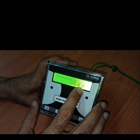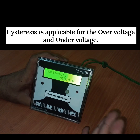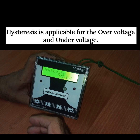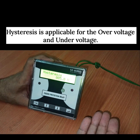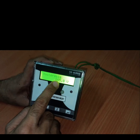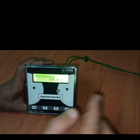Then hysteresis is available. Hysteresis is applicable for over voltage and under voltage. Hysteresis basically means that suppose the relay experiences under voltage and the relay has tripped or is in the tripping zone, and it comes back to normal. So if the under voltage setting is 80 volts, then when the voltage goes above 85 volts, the relay will consider it as healthy. So this is the function of hysteresis.